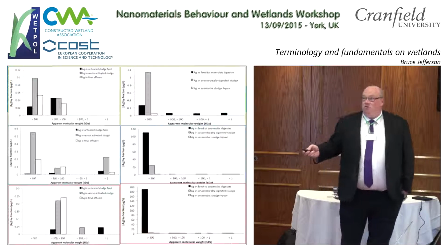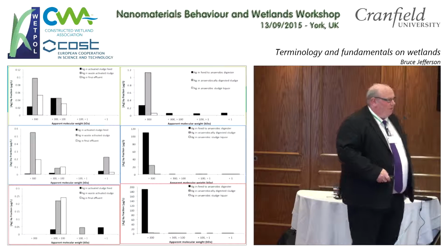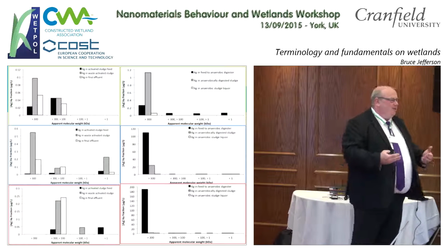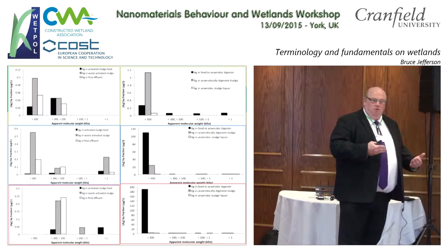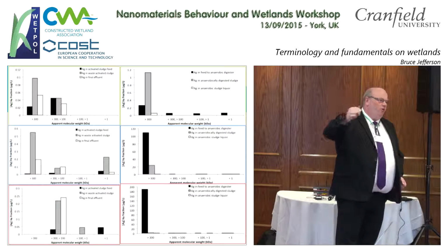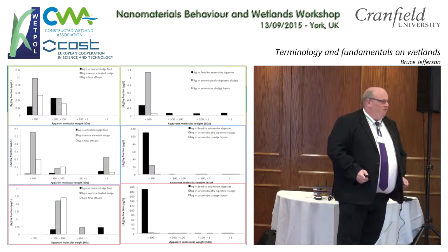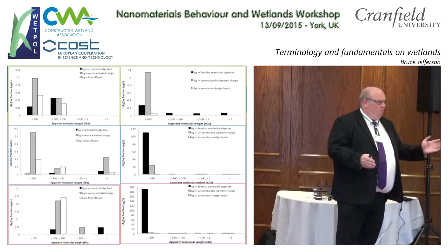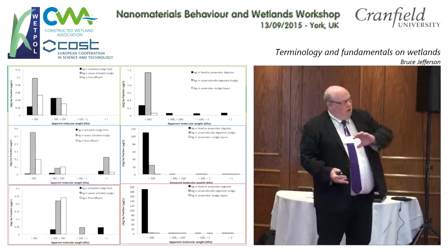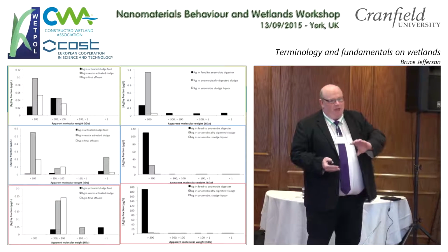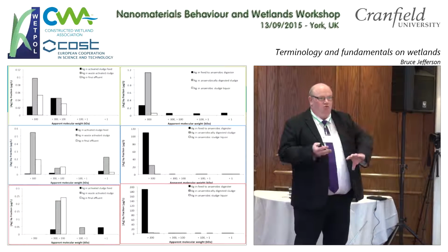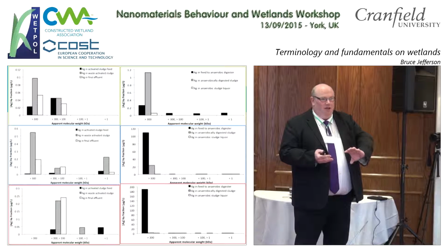So we did do some colloidal fractionation. I was told I wasn't allowed to talk about membranes, but I have to here. We used membrane filters to fractionate out the colloidal fraction. So we'd taken off the 450 nanometer fraction with a standard filter. We discarded that and then we analysed subsequent fractions. In this sort of experiment you have to make sure that you only filter half the volume, otherwise you concentrate the material and it becomes a much finer filter.